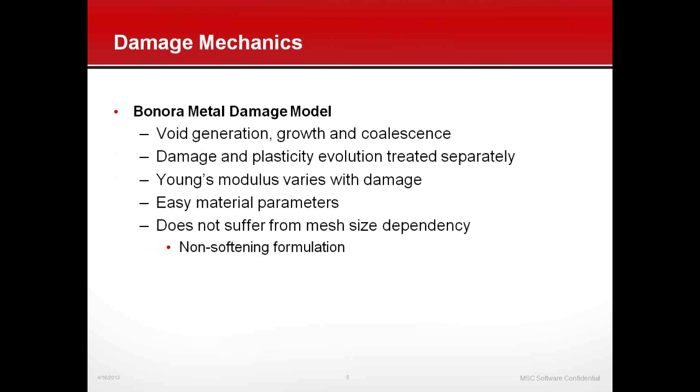The damage evolution and the plasticity evolution always work together with plasticity, but the evolution equations are separate for the damage and the plasticity. One special thing with it is that the Young's modulus is varied with damage, which is one of the key features of this model. Another important property is that the material parameters are easy to determine, straightforward, which of course is very important when you need to determine them.